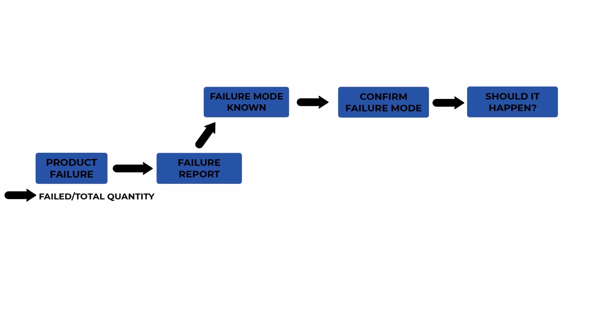gather more information on what could have led to this failure. Depending on the failure, you will measure the components, check the tolerances and tolerance stack up, investigate the assembly process, look into the defined loads, and compare them with the loads that appeared during the failure. We will basically not leave one stone unturned until we truly understand the reason behind it.